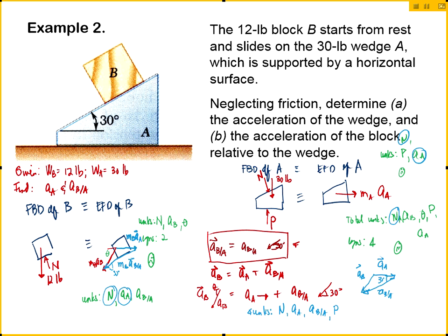There are certain things you have to unlearn from physics, like that tension is equal to mg. That's not true anymore when you're moving. In the same way here, if nothing's moving, you're correct, because for the FBD of the two, the only external forces are the weight of B, the weight of A, and the normal force, which balances them. But in this case, the summation of vertical forces for the two combined is not 0, because they're moving. Yes?